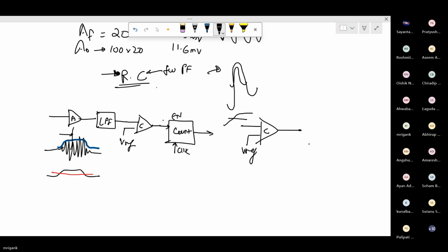Sir, we will provide this signal as the trigger to the monostable multivibrator, and it will be programmed to some pre-decided time duration. Again, I'm not going for digital blocks. I want to do it completely analog. So no counter, nothing. So that monostable thing, how will you design it? Just suppose you have a clock. Clock is possible. So what will be the circuit implementation?